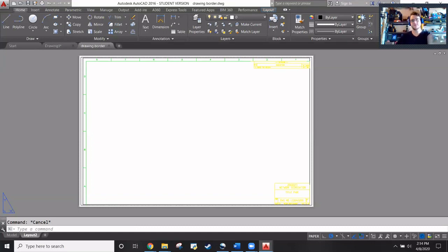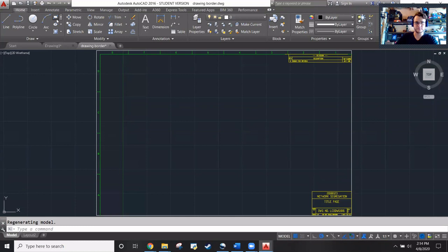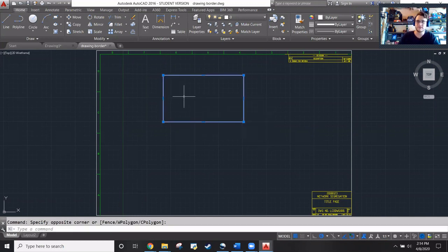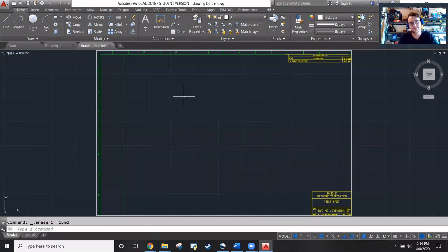In this drawing file, you'll draw a box, and I haven't really messed with this much, but you'll say inside this box, insert this other file. If you don't have both those files loaded up, it'll throw an error. But you can still open this parent file and whatever content is externally referenced just won't show up.